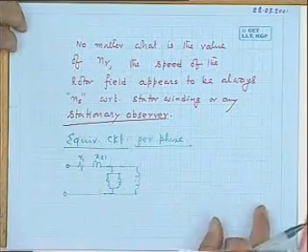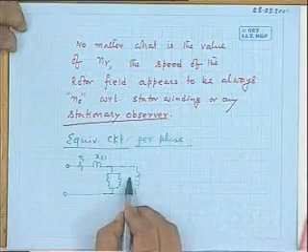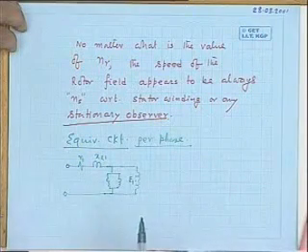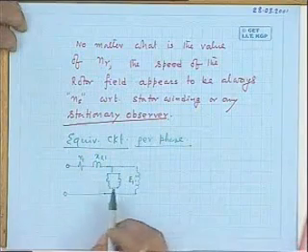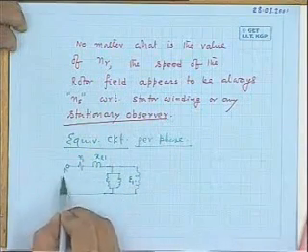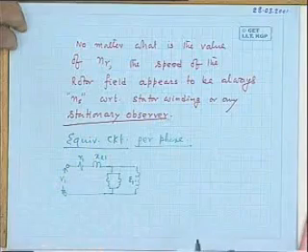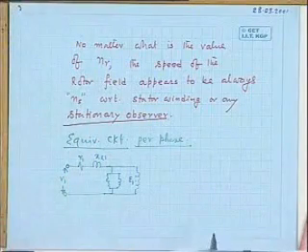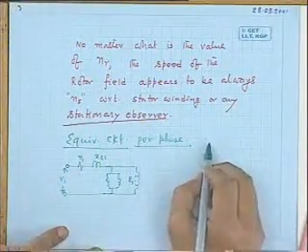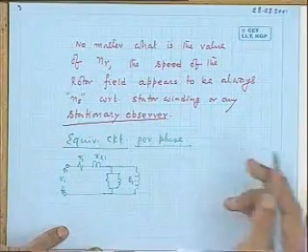And this fellow carries current whenever there is a current on the secondary side. So this voltage is your E1, the induced voltage. And this is your applied voltage per phase on the stator. Let us also assume the machine is running at some RPM, NR, as a general case.